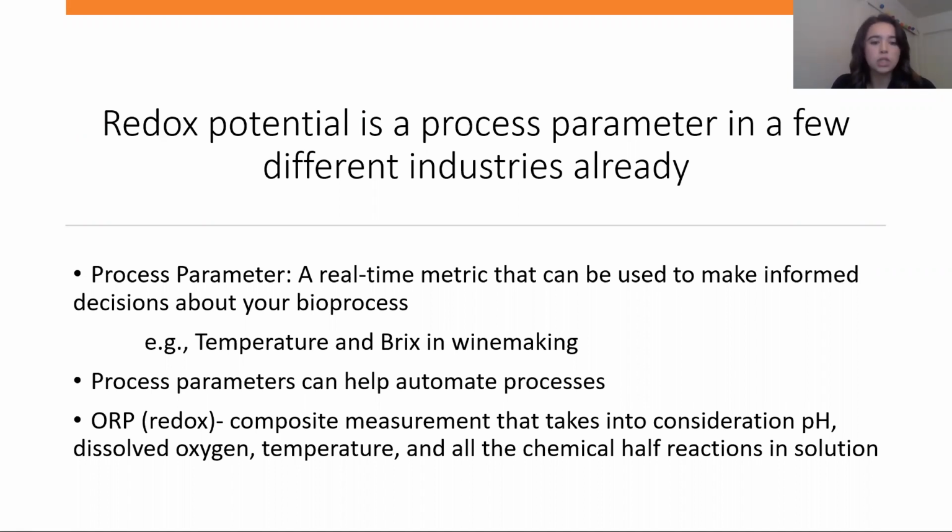But often when we see these changes in Brix, there's a significant delay between when the problem actually begins and when it's obvious enough for us to see it and then try to correct it. So our hope is that redox data will improve this response time as an additional process parameter to use. Redox as a parameter considers pH, dissolved oxygen, temperature, and chemical half reactions.